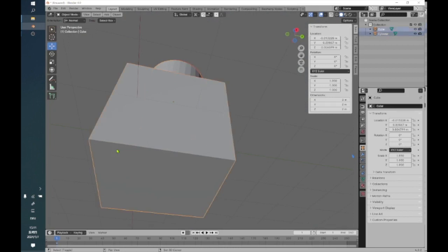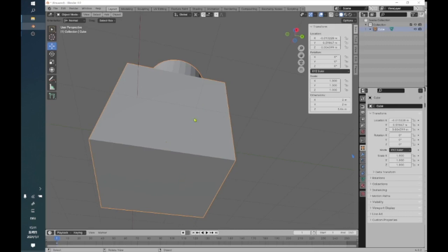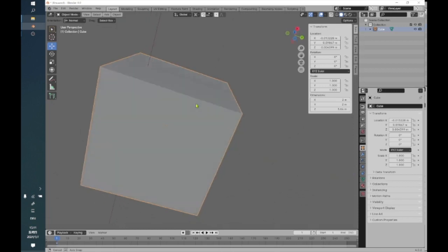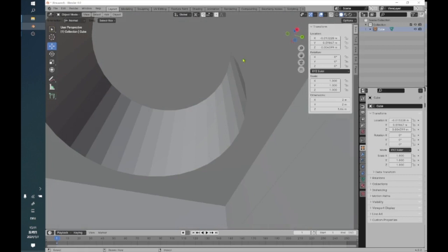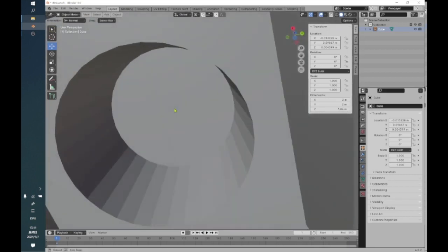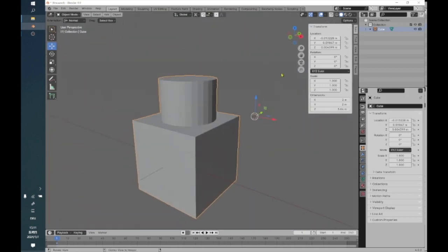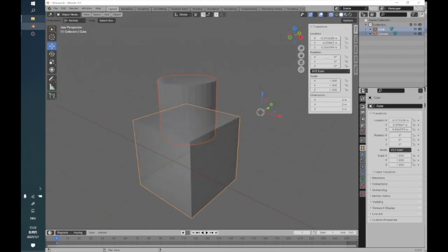So now I select these two objects. And as I said, the sum by the Spice Girls, tonight is the night when the two become one. So the two become one, and outside nothing really changes except that they become one object. But if I look here inside, you can see what happens. This additional cylinder and an additional roof, which was here inside, is now gone. Again, compare in the X-ray mode, so you see now there is nothing here, right? If I go back, you can see that there are two objects, but there are also much more lines. So this is the union.